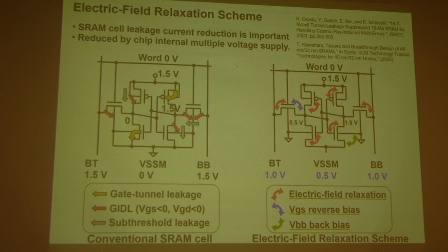When we talk about the leakage, let's say for an NMOS transistor, the leakage happens even when the gate is zero, but you have a non-zero VDS. For example, if this is VDD and this is zero, you have this leakage current. This leakage current depends on the VDS.